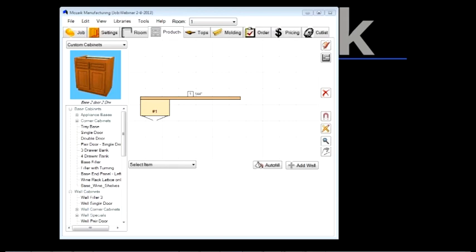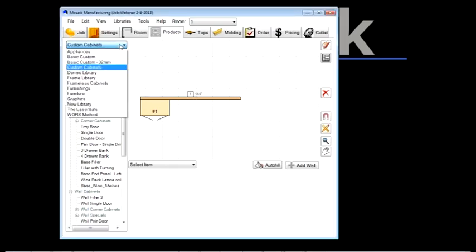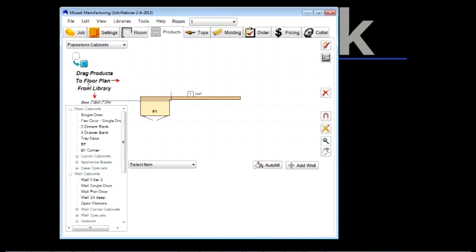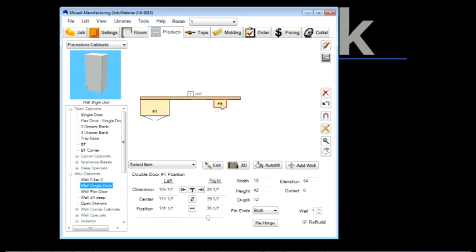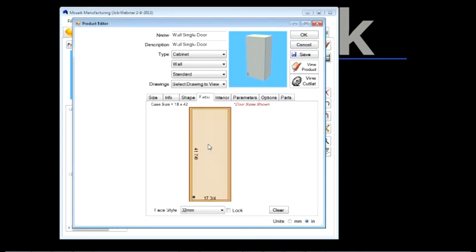It would be for all frameless upper cabinets. So I made an actual library for just upper cabinets, so I can use those parameters. Mm-hmm. But what I'd basically just like to make the reveal, instead of 0 at the top and 0 at the bottom, make it 1/8 of an inch at the top and minus 1/8 at the bottom.